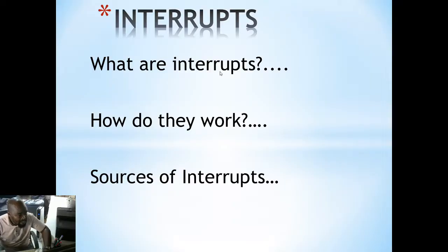That principle still holds for PIC interrupts. So in the PIC microcontroller, how are interrupts used? You will have the main function, the microcontroller executing the program that falls under the main function.